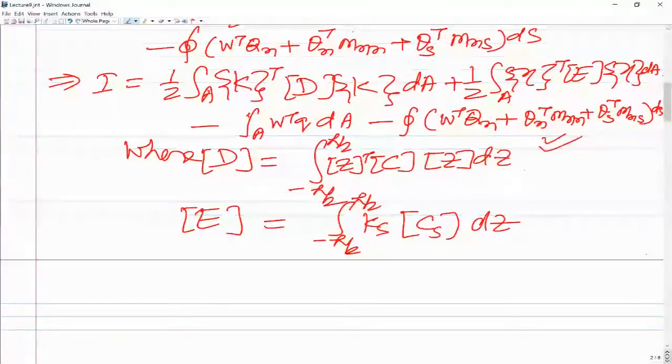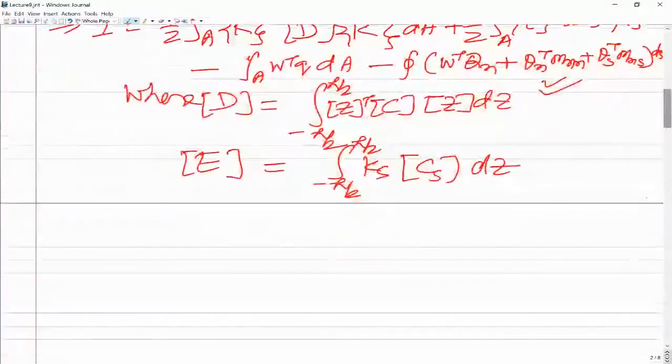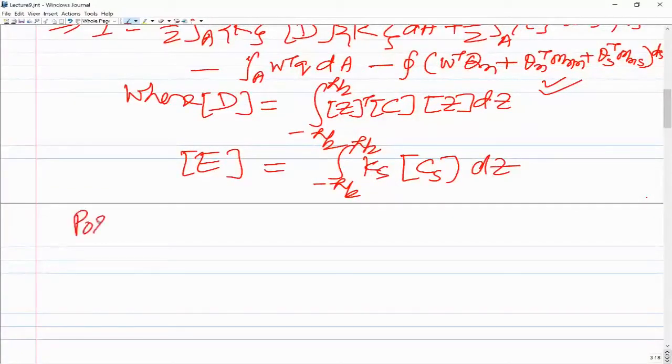So now let us see, although most commonly what we use is the plate bending element for the first order shear deformation theory. The most commonly used elements are the 4-noded isoparametric element and the 8-noded isoparametric element. Sometimes people do use the 9-noded isoparametric element. So these are the most commonly used elements, but let us look at the possible elements, what all we can have.